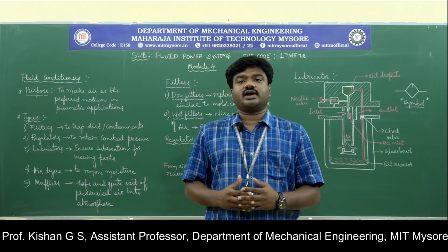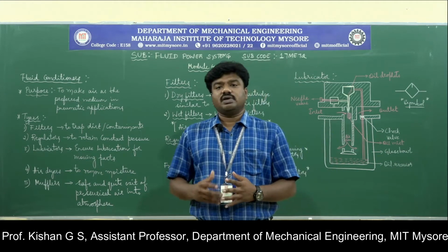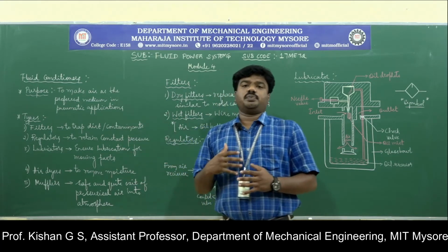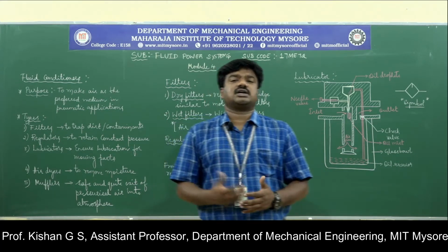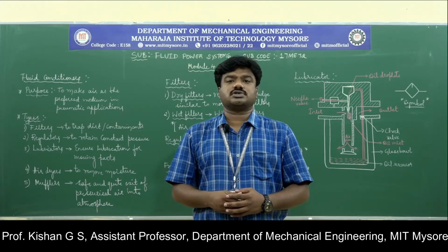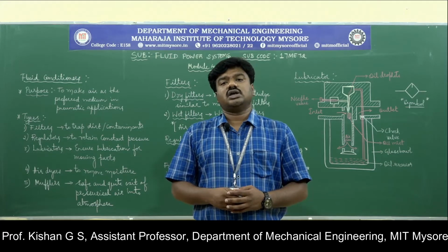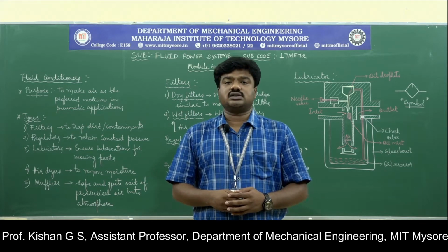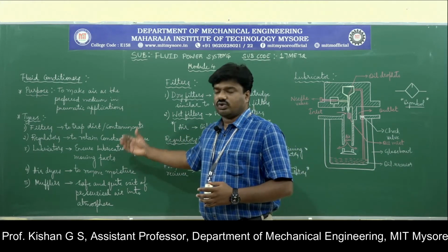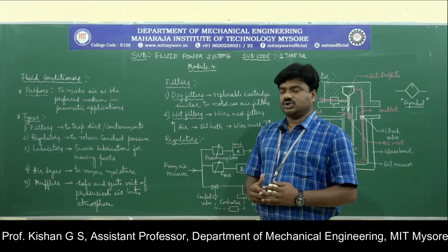Hence the lubricators also play a vital role as part of the fluid conditioners. Keep in mind, if the lubrication adds an excess amount of oil into the compressed air, then the system collapses. Hence a huge amount of care is taken on the lubricator part in the pneumatic system. We are going to study it in detail once we take up the lubrication unit.